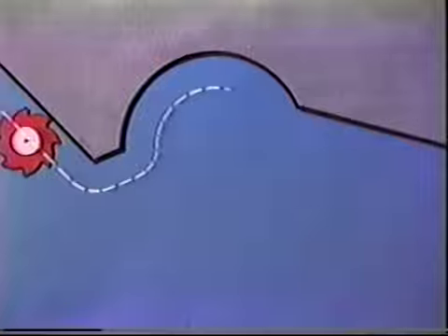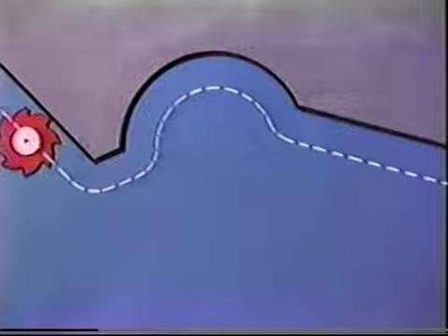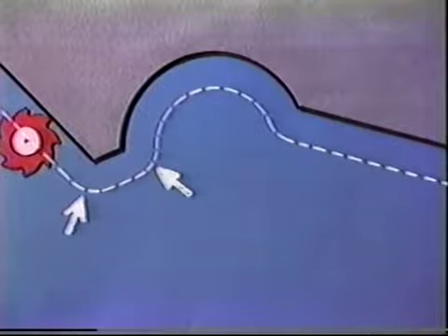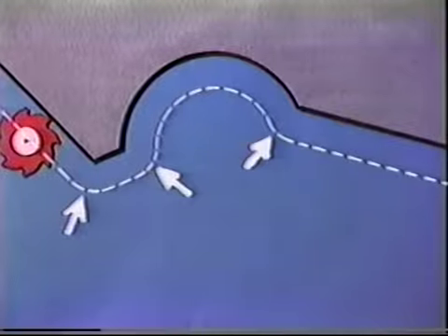To end up with the programmed contour when milling, the center point or axis of the cutter must be guided along a path with the same spacing from the tool as the tool radius. This is called an equidistant path. When this is programmed properly, the control system calculates all the points of intersection for the individual tool paths. If desired, it inserts blends at irregular contour transitions. For the control system to do this, it must be told whether the tool is to the left or right of the contour in respect of the milling direction before moving to the contour.